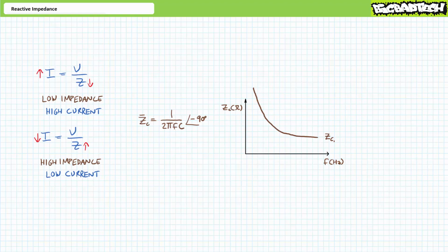After the transient charge phase ends, a capacitor essentially appears like an open circuit or an infinite impedance. After a capacitor is fully charged or fully discharged, current flow ceases. The complete halt of current flow perfectly defines a high impedance element. This makes sense. Above DC or 0 Hz, slowly oscillating waveforms present slowly changing voltage.